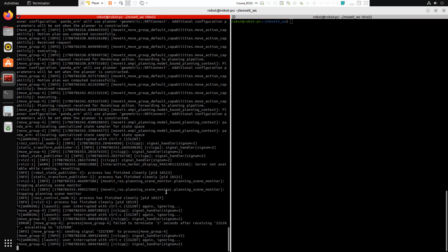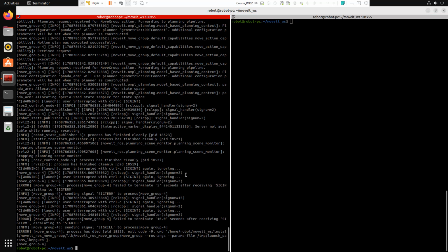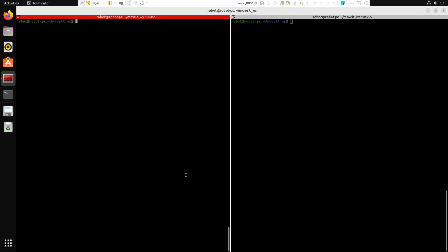Yeah, so I just want to show you the final demo. So these two things are with the programming. Okay, there are not many changes. You can use the Move Group and also the MoveIt CPP and MoveIt Python. Okay, so we can see the last example, which is a demo connecting Gazebo and MoveIt. Gazebo is the controller server and MoveIt is the controller client. So when you press the execute button, it will be executing in Gazebo. Okay, I will explain it after that.